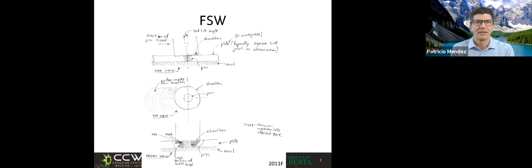And there is no melting. You can reach melting if you overcook the part, but then you ruin it. So when you do it right, there is no melting. The original patent mentions no melting. And by the time this is done, you end up with a microstructure with a very fine grain size, really good mechanical properties, and no solidification defects. What else would you want, right?